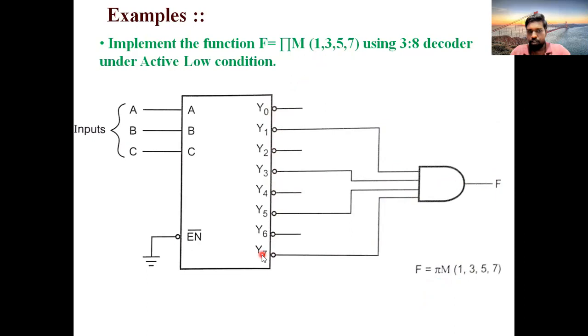Okay, the same format. The point you should remember is whether the given condition is active low or active high. Active high means directly draw the lines. Active low means add bubbles to the lines. And as per the given condition, you connect them with a particular gate. So we take 3 inputs here, and as per the given question, these are active low conditions. So take the low outputs and connect the given numbers to an AND gate.